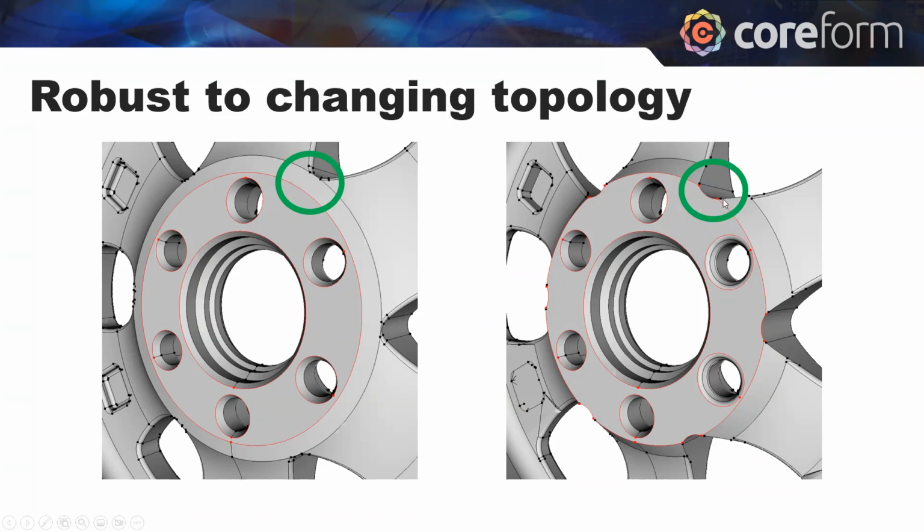it changes the topology. And with traditional meshing workflows, if you'd done a hex decomposition approach, you would have to remesh, and you might even have to completely define a whole new meshing algorithm, like scripting, to get your hex mesh to conform to these surfaces. And so, in fact, we oftentimes don't worry about that. We just build a tet mesh.